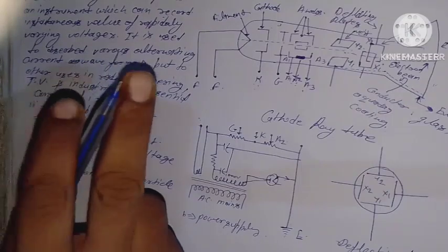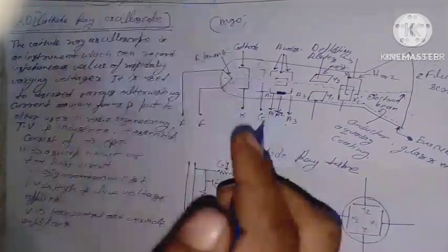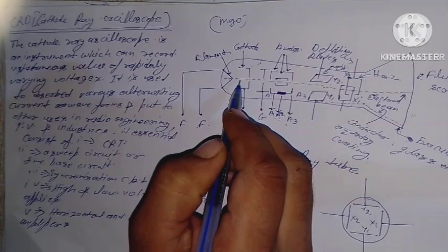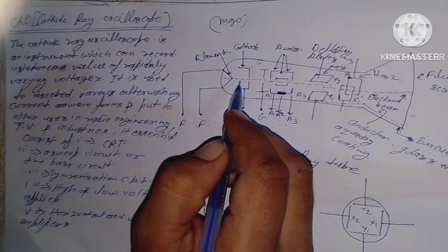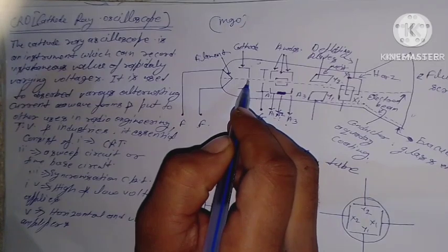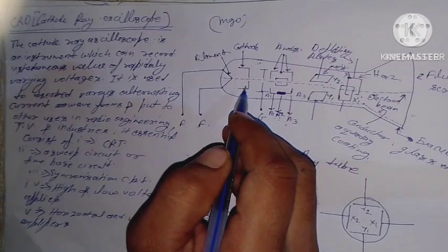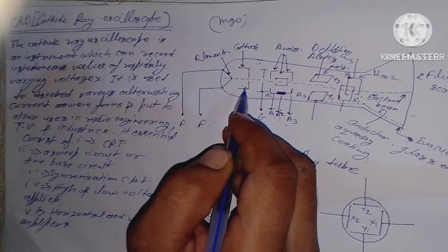The cathode is surrounded by a metal shield in the form of a cylinder, with a hole at the end farther from the cathode. The cylinder is given a negative potential with respect to the cathode, so that the electrons are repelled from it, and any excess electrons join the axial shield or modulator.